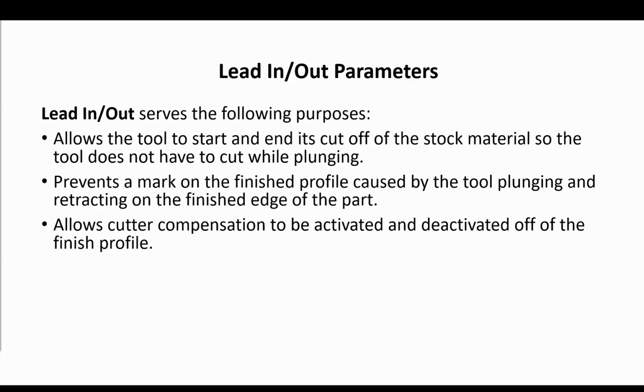It allows the tool to start and end its cut off of the stock material so the tool does not have to cut while plunging. It prevents a mark on the finish profile caused by the tool plunging and retracting on the finish edge of the part, and it allows cutter compensation to be activated and deactivated off of the finish profile.